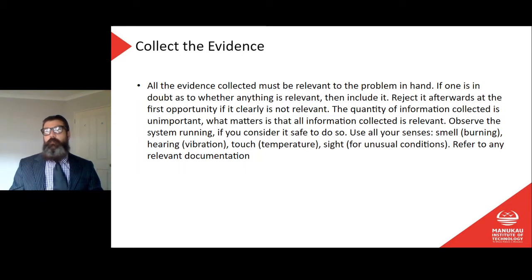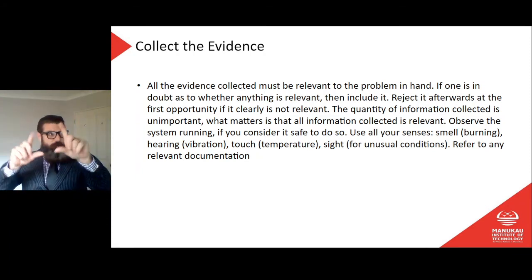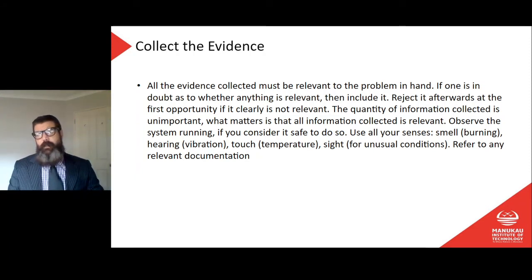Again, an example from my experience. I hate to bang on about the same things all the time, but the experience I have is the experience I have. If I go to an unmanned fuel site and it's got a card machine with a display and then pumps, and I find that the display is blank and also the pumps are not working, but there's power there and no circuit breakers are tripped, then I think, well, okay, what is the common feature here?